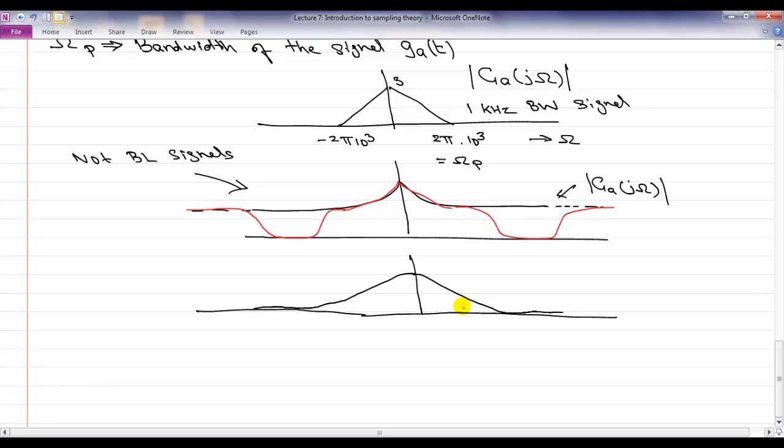The mathematical reason for that, if you remember your duality theory from linear systems class, is that if something has a Fourier transform which is zero after a certain limit, then the signal must go on forever in time. Now, if I am speaking, I can't keep on speaking forever. So just saying that means I can't have a band limited signal.